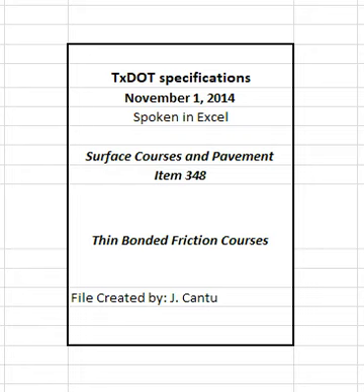5.2.2 Measured percentage. The averaged measured asphalt percentage from each sublot will be used for payment for that lot's production when the measured percentage for any sublot is more than 0.3 percentage points below the JMF target asphalt percentage or less than the minimum percentage specified in Table 8. 5.3 Aggregate. The aggregate weight in tons will be determined from the total weight of PFC less the weight of the asphalt.